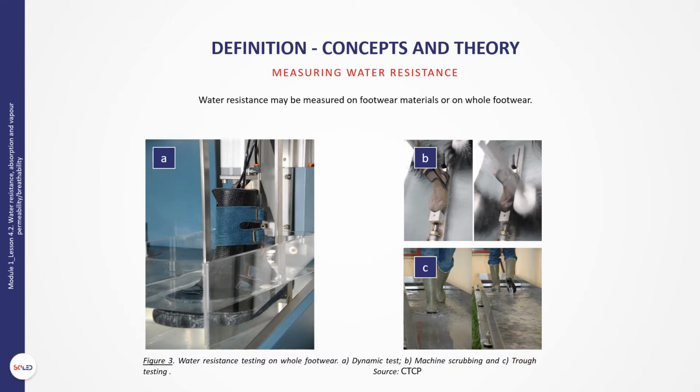The shoe is fixed in a rectangular metal plate with a fixed jaw at one extremity and a sliding jaw at the other to adjust to the height of the shoe. Then 2 brushes situated on either side of the test piece are separated by adjusting a distance, describing a backwards and forwards motion over the whole length of the test piece, whatever its size. The horizontal motion of each brush is completed by a rotational movement, the direction of which changes at the end of each horizontal cycle. The direction of rotation of each brush is the same as the corresponding backwards or forwards motion. The horizontal distance between the 2 brushes system should be adjusted so that the whole surface of the footwear upper touches the bristles.